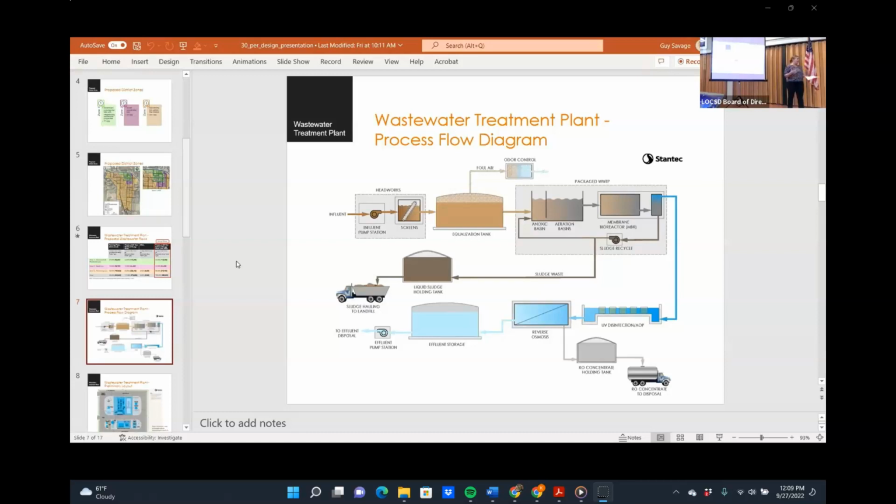This is the process, and there's a bunch of components that go into the treatment plant. The first piece of it is collection, and it's the raw sewage. It's what gets flushed down the toilet, what gets through your laundry. That's what is flushed through the collection system and collected. But when you're working with pumps, you're not going to pump at those diurnal peaks. So you're going to collect it in what we call a wet well. It's going to hold your raw sewage, and it's going to be pumped into the treatment plant so that you have a steady flow, or a relatively steady flow.